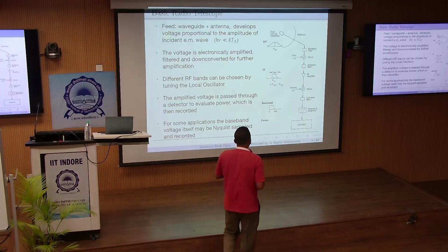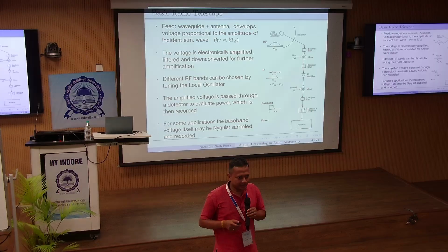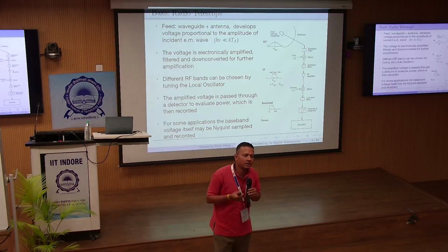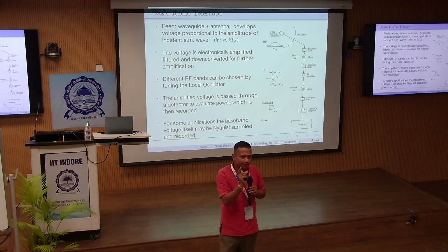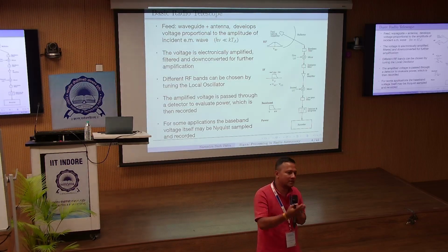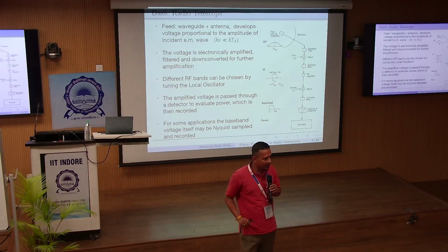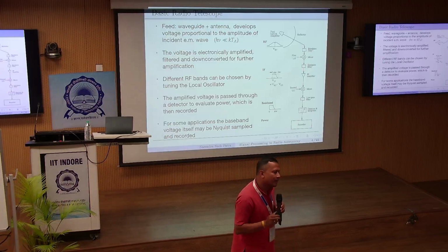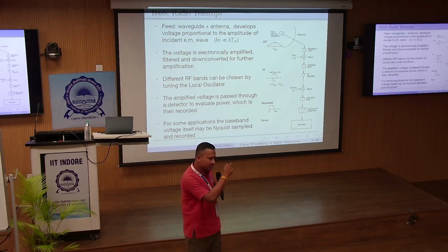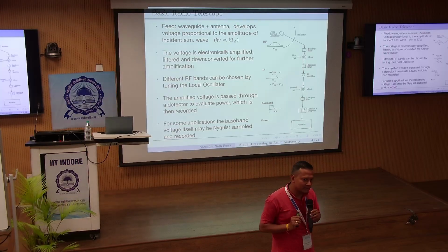Now let us talk about, let's say, GMRT, right? GMRT works from 150 megahertz to 1.5 gigahertz, correct? Now I have a signal which I am interested in, like the H1 21 centimeter signal. Yesterday we have seen H1 21 centimeter is a 1.4 gigahertz signal. So if I want to detect it, I have to tune this whole system to 1.4 gigahertz, right? Now, as Jagdeep was also mentioning, if I want to detect a signal at 1.4 gigahertz, right?